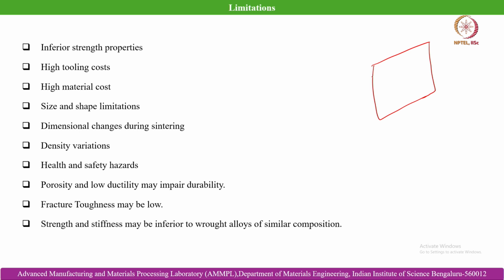Although several particles are sintered and get joined because of diffusion at the onset of temperature, in the grain boundary triple points there are some pores which remain beyond sintering and beyond completion of the development of the part. These pores, often present at the grain boundary triple points, are basically the weak spots, the weak links which are responsible for inferior fracture toughness.